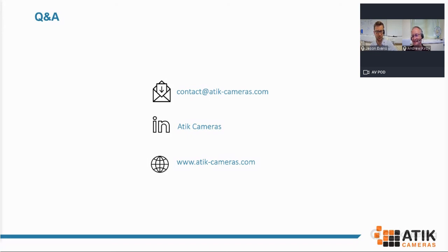In forums, I have found that the binning of some cameras or manufacturers is performed in the software part of the camera, but after this webinar, it's always done in the same way for the main chipset. Going back again, for CMOS it's going to be done in the software, so it's done off the chip, but for CCD it is very much done on chip. Equally, it could be done in the software, but whilst you've got the benefit of doing it on the chip, that's what we would recommend, and that's how we do it ourselves.